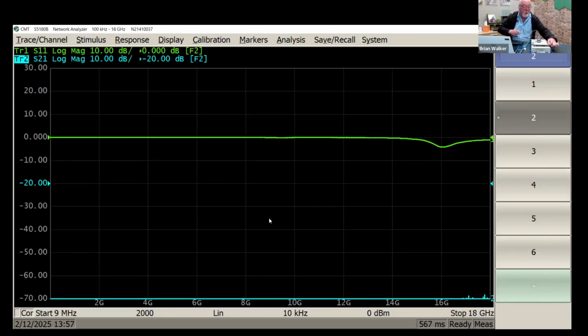Along the top of this board is a pair of 50 ohm lines that are spaced closely together such that it forms a 100 ohm differential transmission line. So I'm going to measure from one side, leave the other side open. Won't be able to do normal frequency domain measurements this way, but I can do time domain and just look through it.